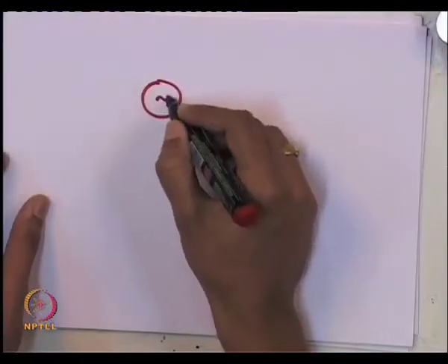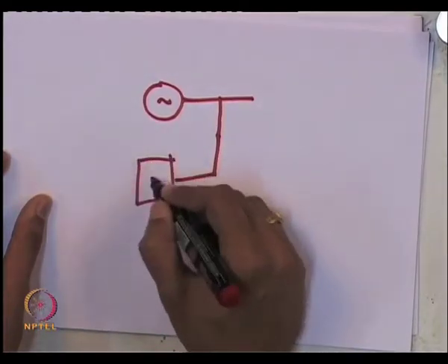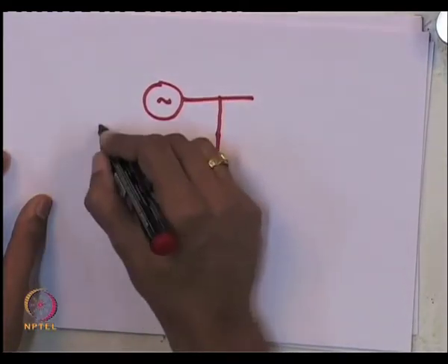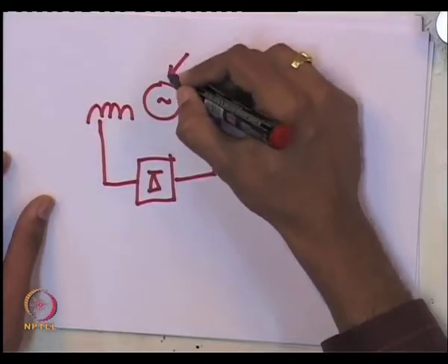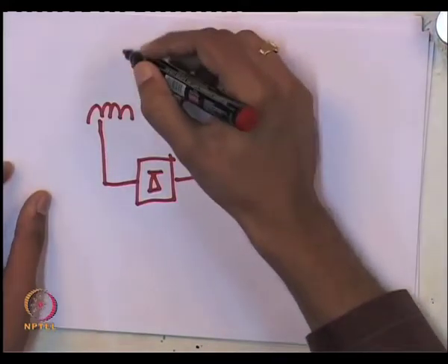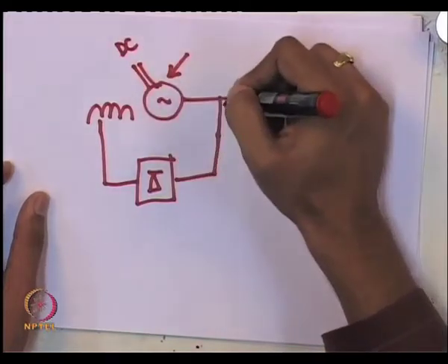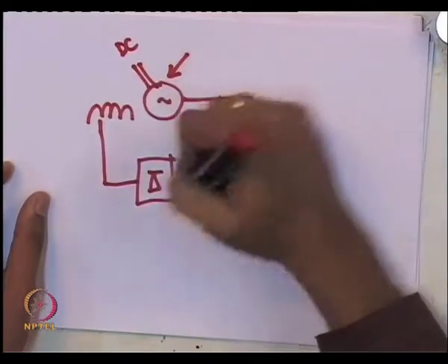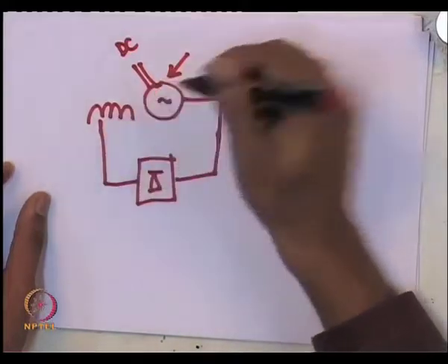So, what I had is a synchronous machine, its output was simply rectified using a diode rectifier and fed to the field winding, and you saw that after a certain speed is acquired by the synchronous machine, of course driven by a DC machine, you find that there is adequate voltage to trigger a kind of positive feedback, the self excitation phenomenon.